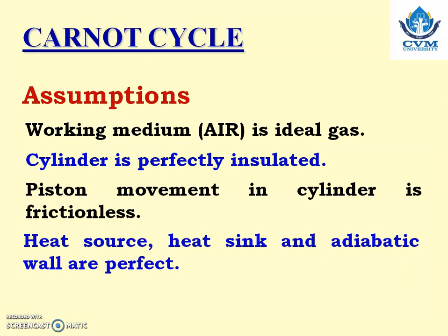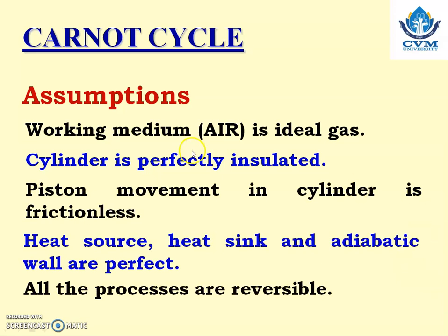Now the assumptions that we have studied are again: the working medium air is an ideal gas, we have already studied. The cylinder is perfectly insulated. Piston movement in the cylinder is frictionless. Heat source, heat sink and adiabatic wall are perfect. If they are not perfect, then there can be heat transfer, right? And the last one is that all processes are reversible. So all assumptions we have already studied. Clear?